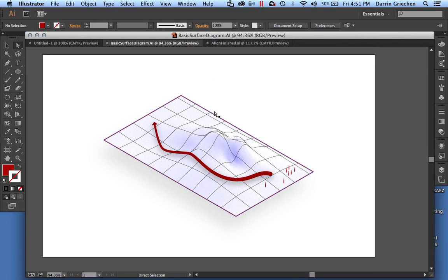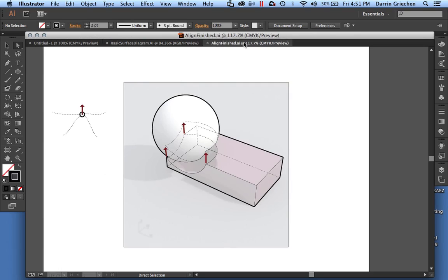And I'm going to show you how to create this diagram fairly quickly within Rhino. We'll create the surface. We'll make these lines that we can bring into Illustrator. We'll add these additional lines here, and we'll also add some people and entourage very quickly. It's very important also that we'll talk about the line weights, and you'll notice that both of these feature very strong outlines.